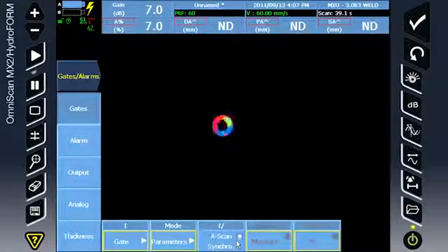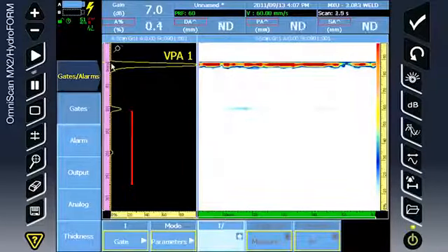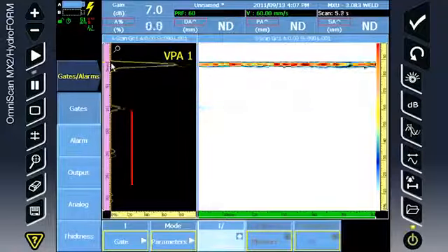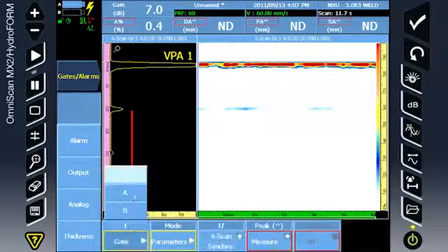This will ensure a flat interface and will ensure, regardless of probe instability, that each focal law starts at exactly 0. Shake the scanner slightly to remove the bubbles.